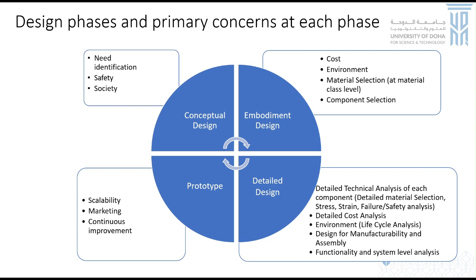So, for example, you cannot change its diameter or its other properties that are going to change the stresses within the component, right? So at detail level, yes, you can carry out a material selection, but that will be for a very narrow class of materials that will all meet that specific requirement.